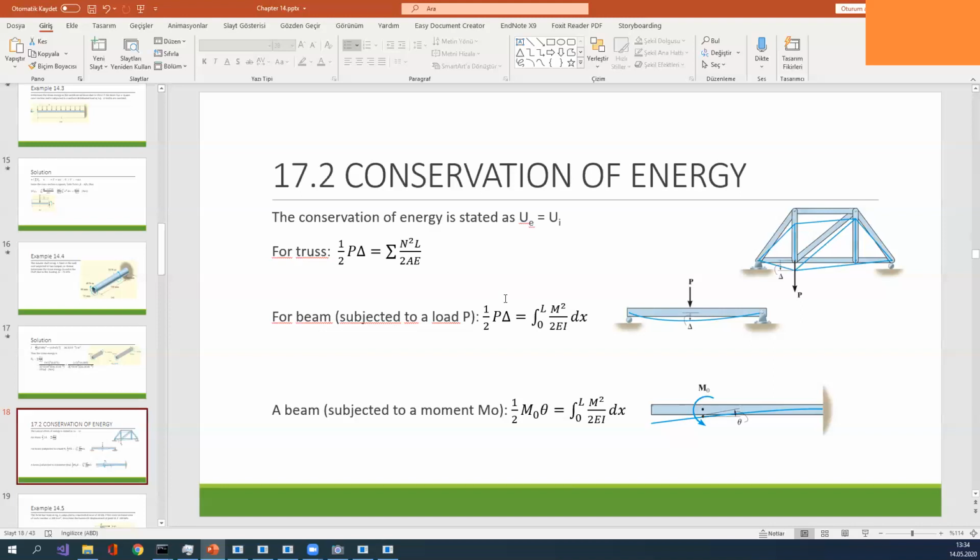Therefore, we always eliminate the shear strain energy. Also, torsion energy is extremely small compared with the bending energy. Therefore, we focus just on bending and axial load. Also, we don't combine bending and axial load; we have to solve them separately.